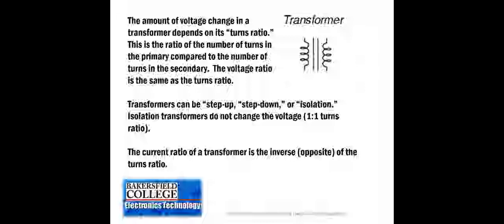Without that isolation transformer, when C1 closes, C3 and C2 open, we're going to create a lot more heat, and a lot more load and stress on the time delay contacts. If you want to, why don't you pause the presentation at this point and look at the control circuit portion of it, so that you can see how the breaker switches in the wires are allowing us to connect.